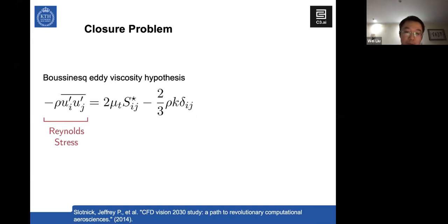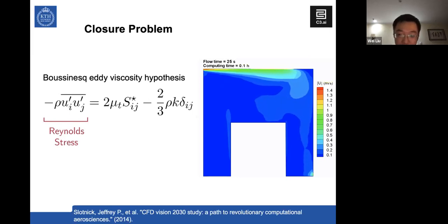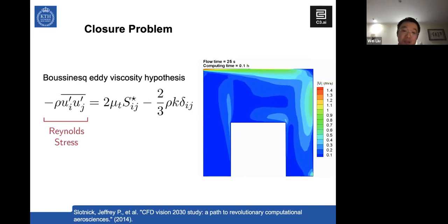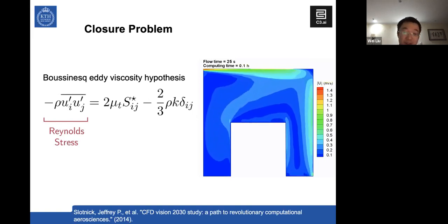And also, the problem with CFD simulations in the built environment is that even with a small indoor domain, the airflow is quite complex. So it makes the RANS simulations especially demanding in the design process with numbers of scenarios. Okay, and the RANS model is also not that fast with a big computational domain.